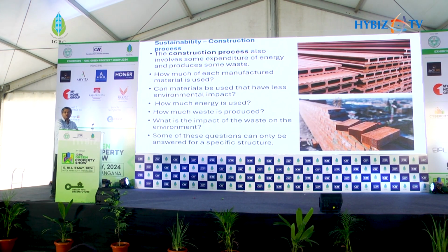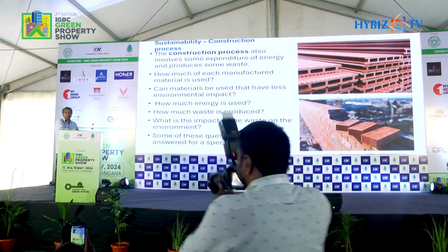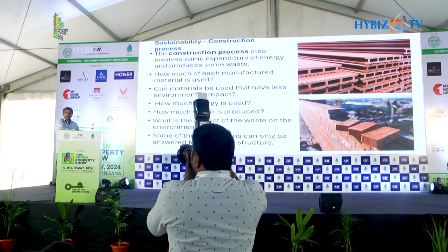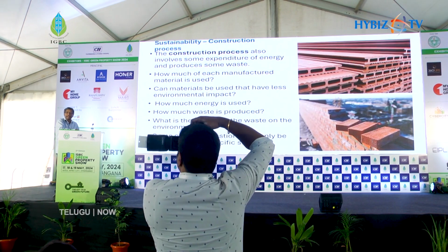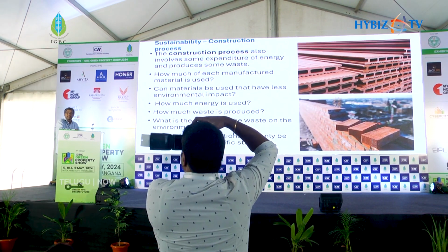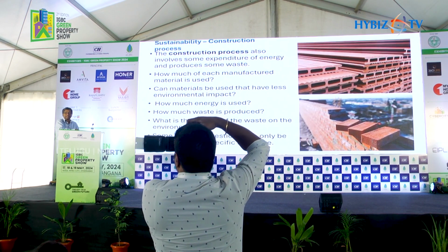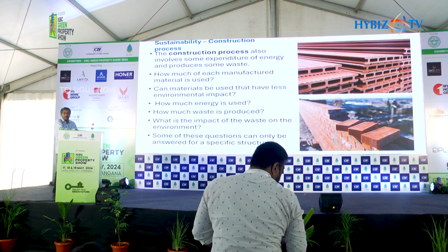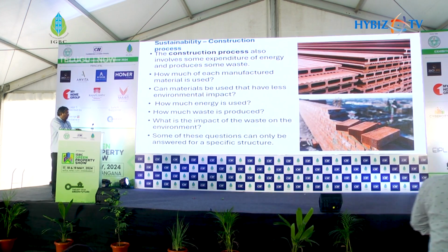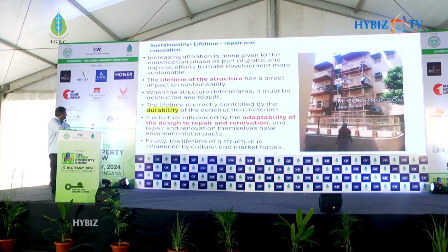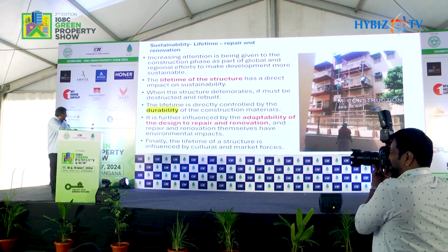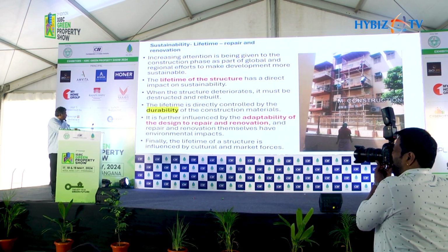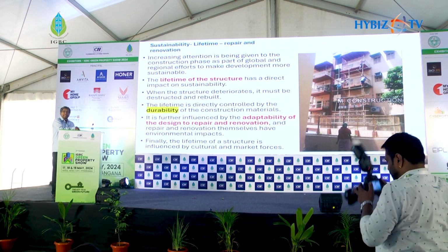We have been watching that while producing clay bricks, there is wastage to an extent of 20 to 30%. While producing autoclaved aerated concrete blocks, AAC blocks, there is 40 to 50% wastage, but this wastage is again used in road fill material and so on, but it should be reusable. The lifetime, repair and renovation of the structure has a direct impact on sustainability. The most important point here is that the lifetime is directly controlled by the durability of the construction material.